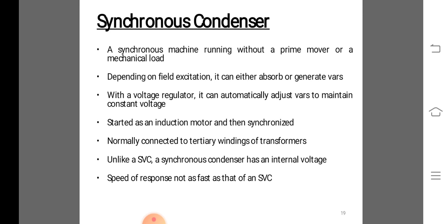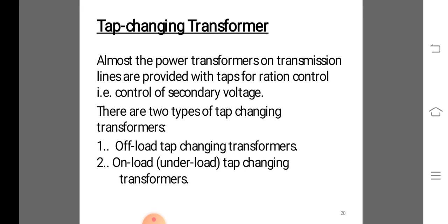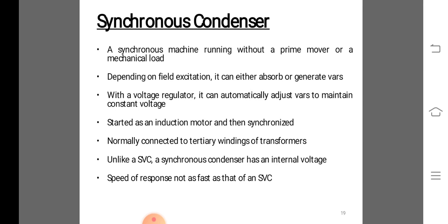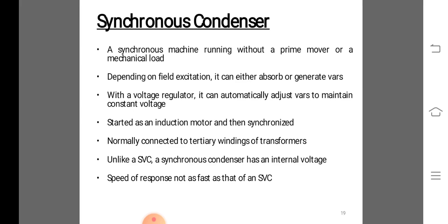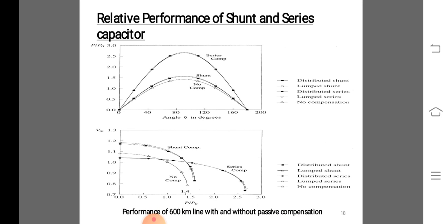The current flowing in the inductance would be different in each half cycle, varying with the conduction angle such that each successive half cycle is a smaller segment of a sine wave. Then the fundamental component of inductor current is reduced in each case. Then the fundamental component is adjusted by giving a proper step input to the firing angle control. A static VAR compensator, when installed, reduces the voltage swinging at the rolling mill and the system buses in drive.